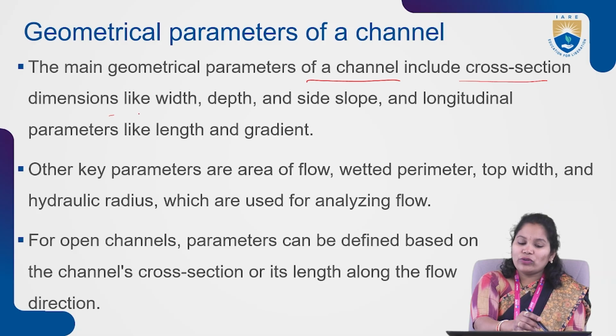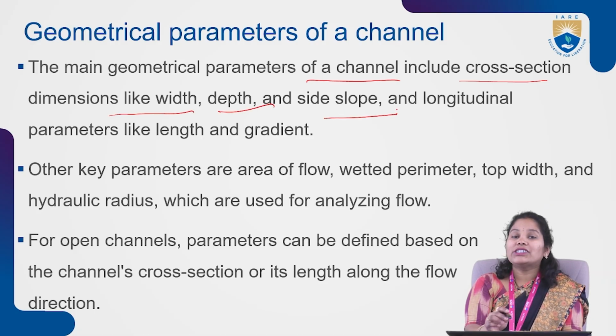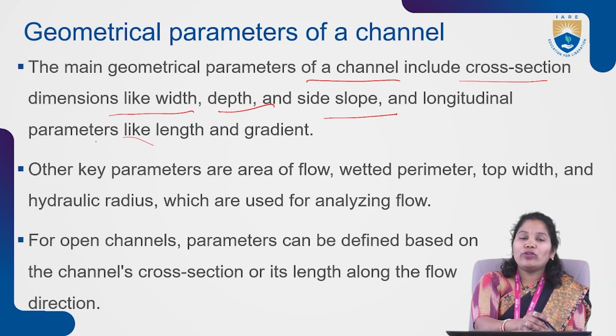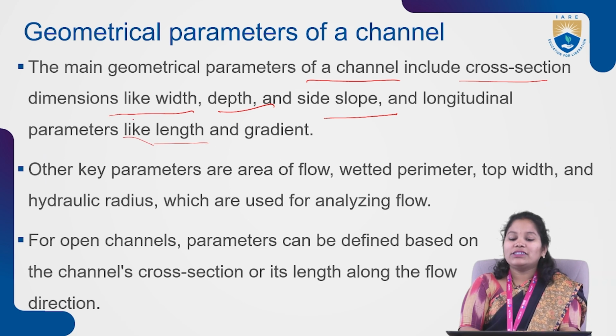We need to know the width, the depth, the side slope, and the longitudinal parameters like length or gradient. All these things we should know to design a channel.